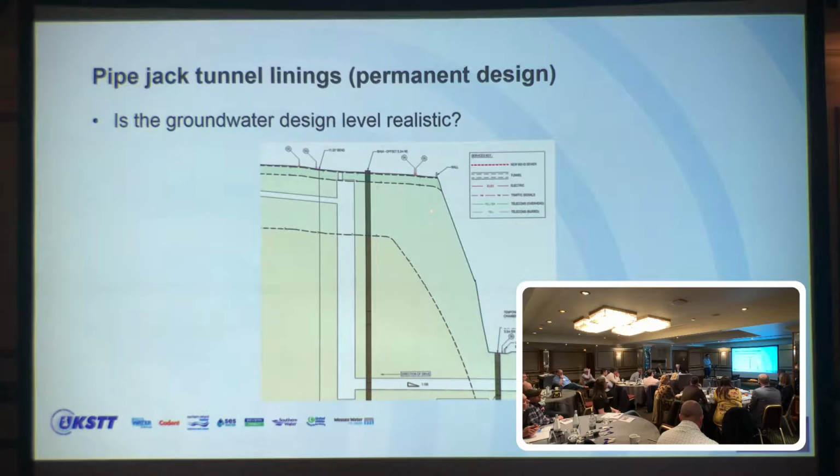But you can see there, this is down in Ramsgate. You can see that you've basically got a cliff face there, and you've got the bedrock down here, and then you've got the superficials above. So when you looked at it, this is a chalk cliff with smugglers' mines in there. You can actually see where the old adits have been put, and you can see water runs out there.